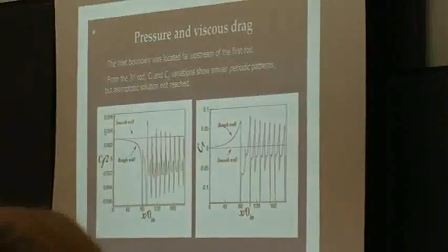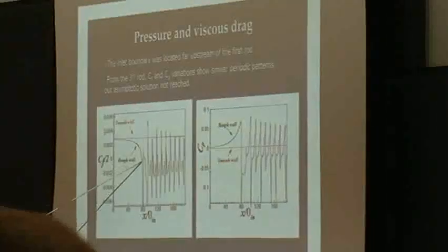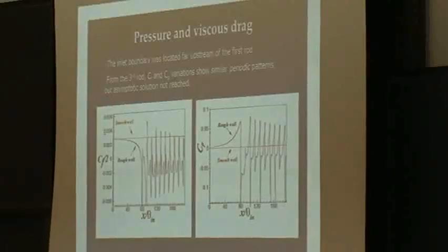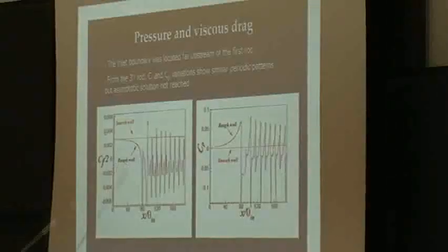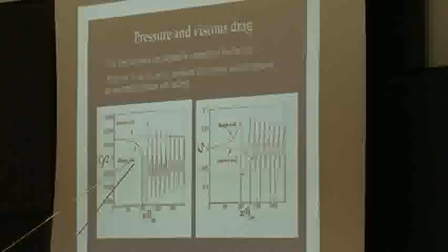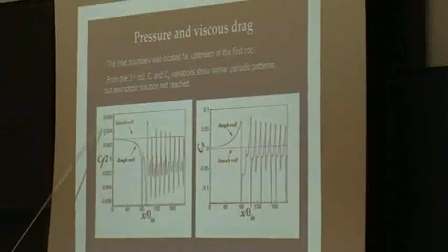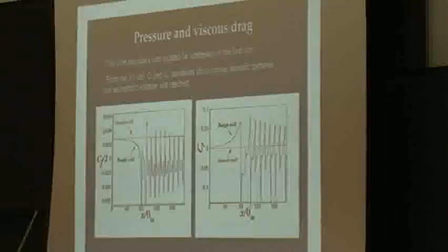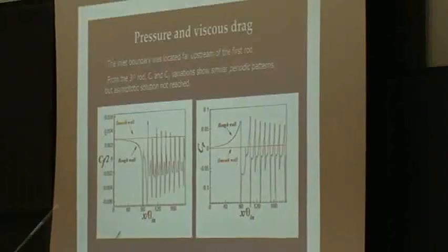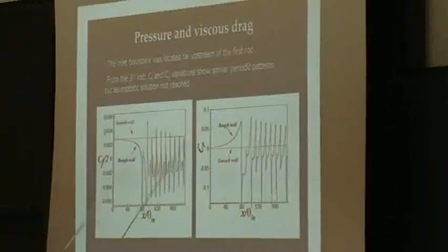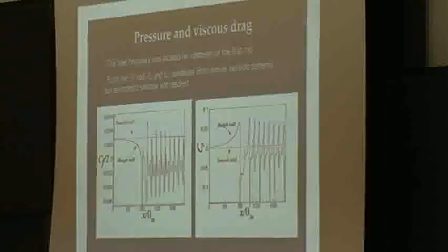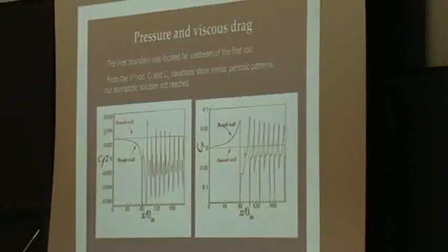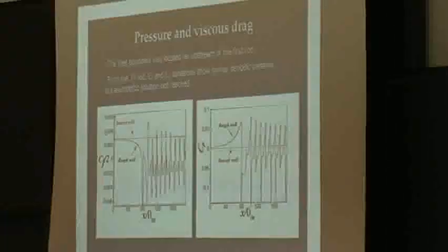And here is what happens as the flow meets the first roughness element. You start to get a large change in the skin friction, and you should observe that the skin friction goes negative. But also look at the scale here compared to the drag due to the pressure across the roughness elements, and you see that this is at least an order of magnitude higher. And then it turns into some sort of a regular pattern.